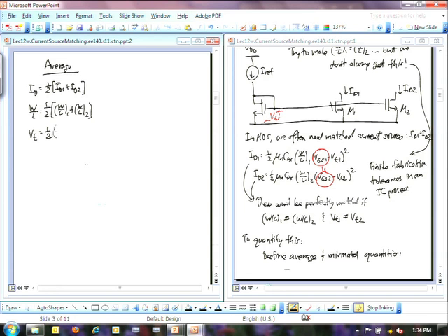And so on and so forth: I can have a delta W over L over W over L. Let me make a better looking delta for you. Taking NMOS device 1 in this case, ID1 is equal to ID, the average quantity 1/2 of ID1 plus ID2, plus delta ID over 2.